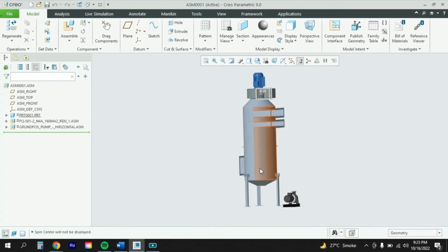So the dirt air will enter into this chamber, and after entering here, because of the low pressure fan, the dirt will move upward, and there will be filters here. So if the dirt is too much, if it is dense, you can use two filters here, and if the dust is not that dense, you can use only a single filter here, and those filters would be removable. So after some time, like in a month or two, you can open it and replace those filters, and the fresh air will be coming out of this outlet of the low pressure fan.